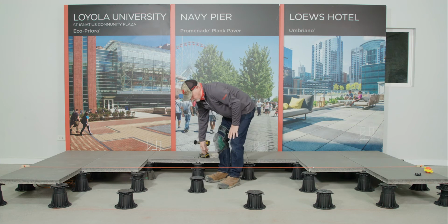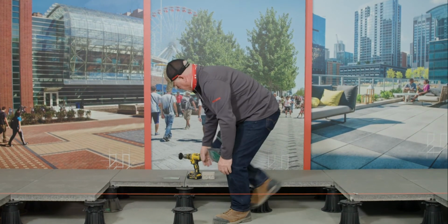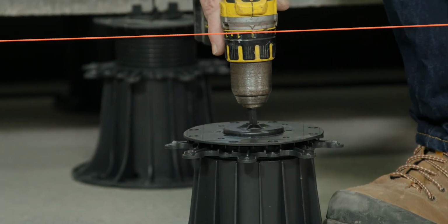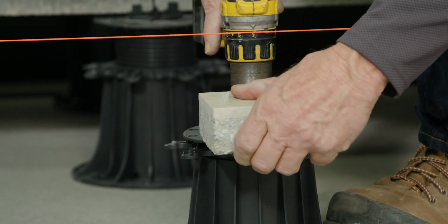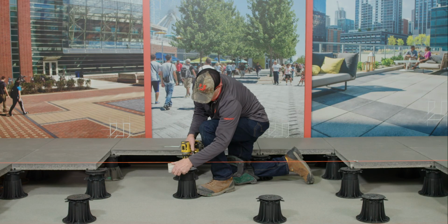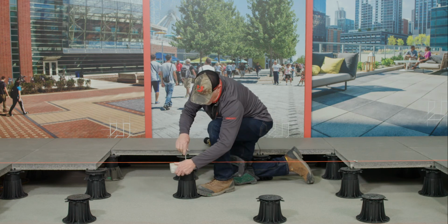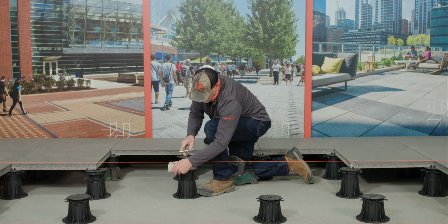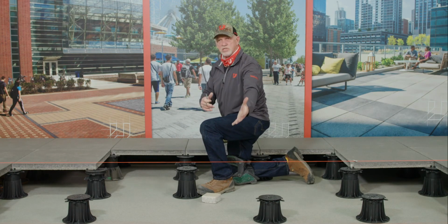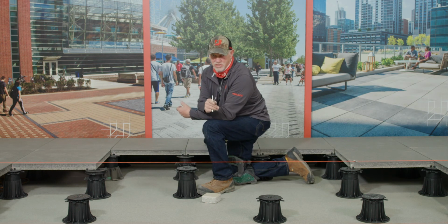I can accurately move that pedestal in, center it down that dry line here on this cross joint coming out, and put a little downward pressure on that pedestal. Now, I'll take the piece, bring it up to the surface of that line, come just slightly below, and fine tune it with the alignment key to accurately bring it right to the point of contact of that dry line. So an easier way as well. Different ways to do it. Not necessarily one is right or wrong; it depends on the circumstances of the job site that you're on.